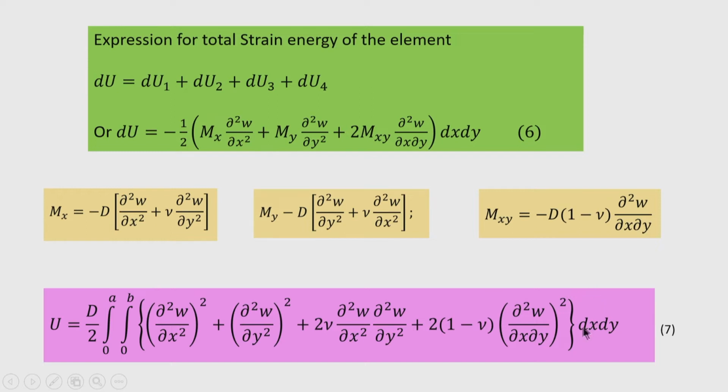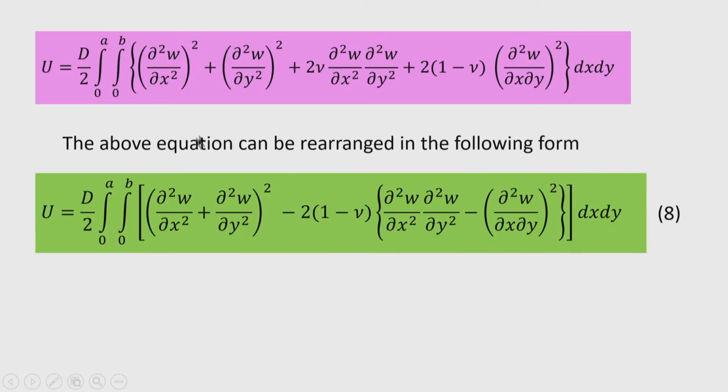This is the most useful expression for solving the plate problem, because solving the plate problem using the Rayleigh method, the approximate method, or any other Galerkin method requires a first approximation of the deflection. Therefore, this form of the strain energy is very convenient for plate problems. Now, this expression can be written in another, very convenient form, from which some physical interpretation can be done, and the strain energy expression can be simplified for some cases.